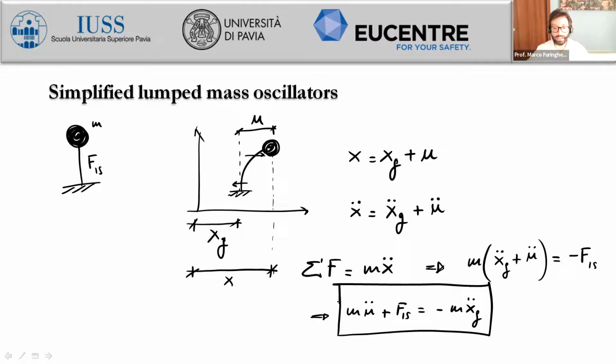So we will start now from the general theory for time integration. As I mentioned on Tuesday, we just apply an explicit time integration method, which is actually the least accurate that you can choose because it is not iterative. The solution is just given at the first computation at each time step. So it is not so accurate, but the accuracy of time integration methods directly depends on the size of the time step.